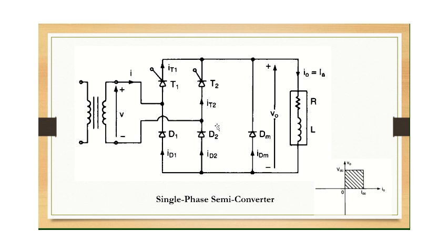Say, at the moment the input signal becomes negative here, what happens? That is the time when the freewheeling diode DM will be forward biased. So the energy that is stored in the inductor will be bypassed, or allowed to flow through this freewheeling diode, which is now conducting. That will cause T1 and D2 to turn off during the negative cycle. I hope you are with me.